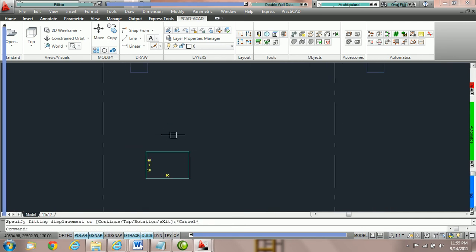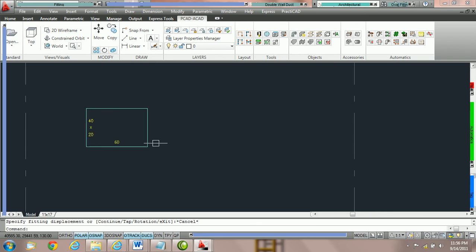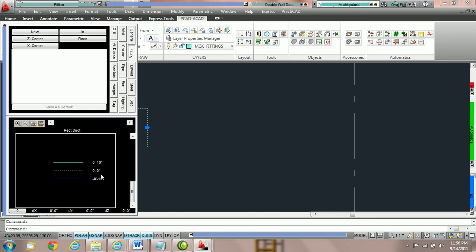Now, after you've done that, click on the duct and look at the elevation. Notice that the center of the duct is at 0, 0. The reason why is we set the elevation, we didn't have Replace Z on. So we set the elevation, and the second we snapped from and used that steel line, which is at 0, it reset the center line elevation of this duct.